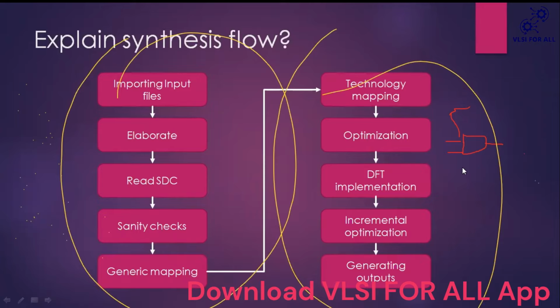They will give these through SDC only. And there will be area targets also. A particular design should fit in 600 by 600 microns, like that. All these targets will also be provided through SDC. The tool will take those targets and try to meet them during optimization. All this optimization can be done in the generic stage and the technology mapping stage.